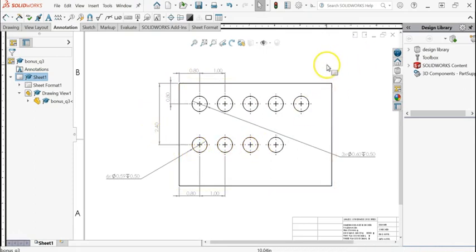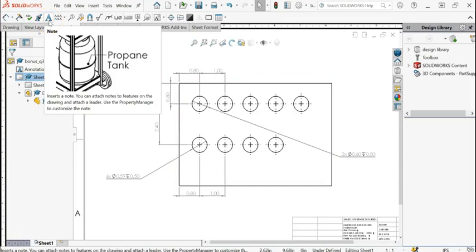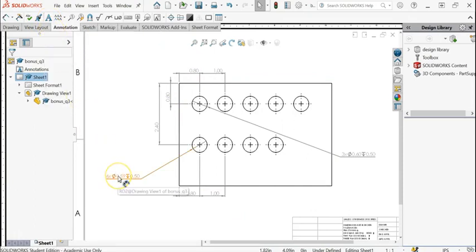So how do I go about showing which one of the circles is what diameter, and how do I avoid this drafting being overcrowded, over busy with lots of dimension lines? One way you might think of is, I use some tags and notes and call this dimension A, and on all of these that share the same diameter, I say these are A's, and the other circles, maybe I call this B, and the other circles that share the same diameter, I call them B.